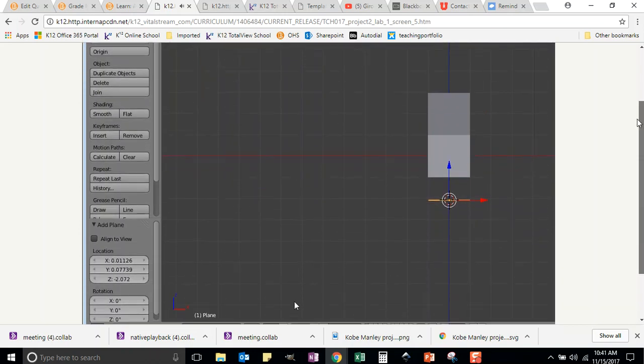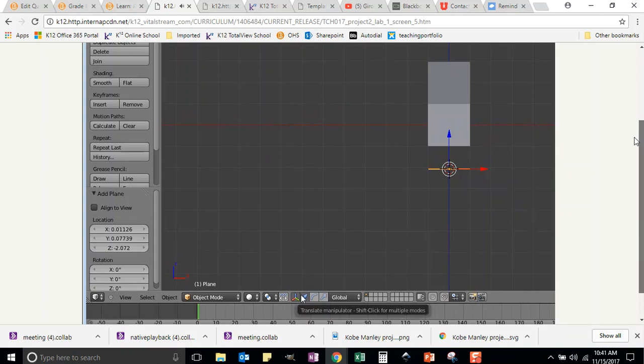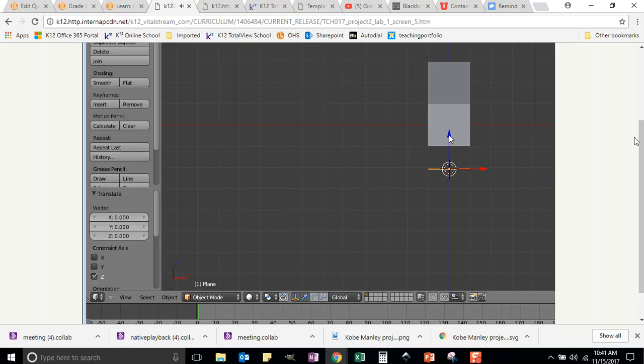Make sure you still have the Transform Manipulator Mode button selected. Left-click the 3D Transform Manipulator's blue arrow. Move the plane to the bottom of the original cube. Left-click again when it is in the right place. Left-click the Scale Manipulator Mode button. Left-click the 3D Transform Manipulator. Scale the plane until it is about 6 boxes wide.